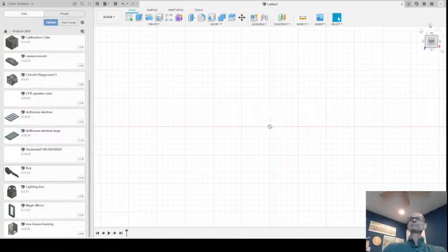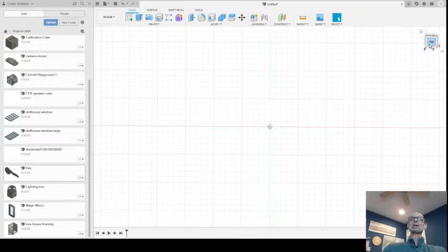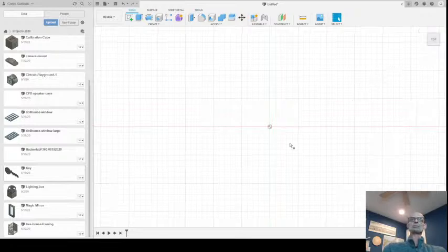And you can reset that view to top, so that when you're looking at that, you right click and reset this current view as top, to make sure that you're looking at the top of the object. And that just helps with alignment if you are going to put it on a CNC machine or a 3D printer or what have you.